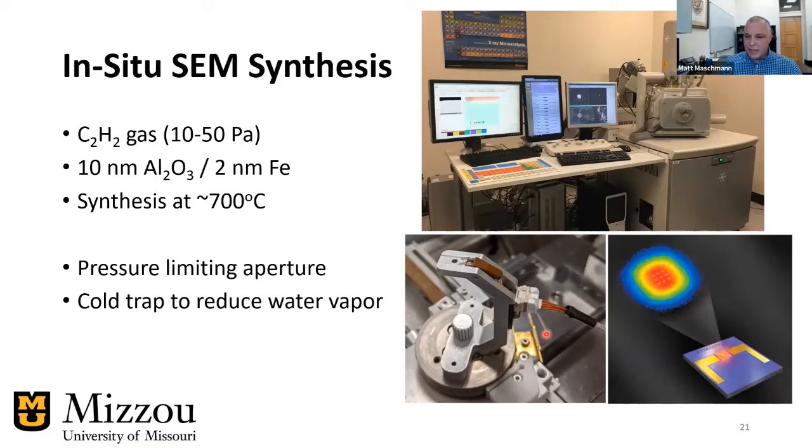And it's not present here, but right here where this hole is, there's a MEMS heating device. It's just a consumable chip that you would then place on that holder, and it heats up. So it heats up locally if you go to the right bottom image here. This is what the protochip itself looks like. So there's electrical contacts, and it's heating up a very small portion of that chip. So something like 100 by 100 microns is the actual uniform heated zone on this chip.